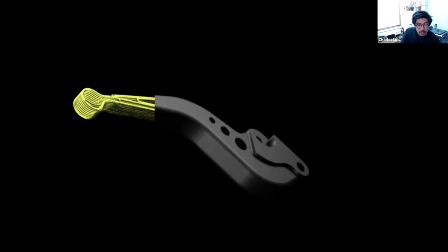Nylon can be recycled. Why not nylon CF? It's just that nobody wants to recycle a material that contains carbon fiber. Eventually, theoretically, there's no reason why you couldn't. But nylon as a polymer also does degrade with each recycling. Theoretically, you could take nylon CF, blend it up, make it into pellets, but you'd have reduced uniformity. Eventually, I would love to see it recycled, or maybe if we didn't use nylon, we'd use another polymer.